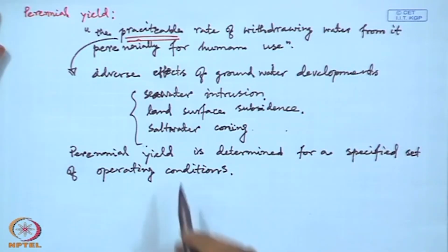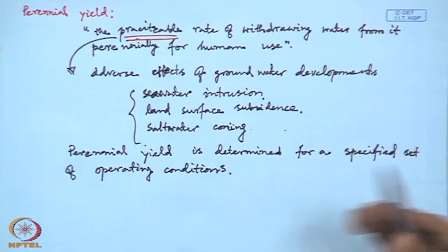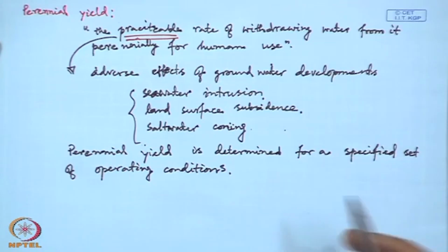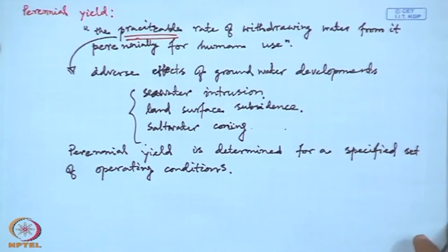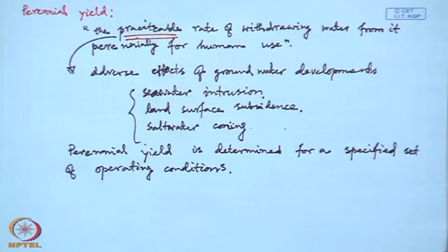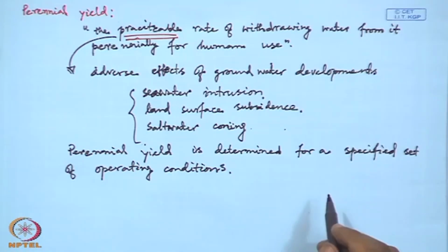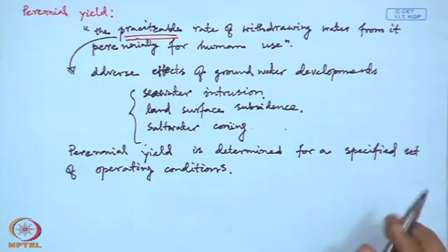So, this perennial yield is similar to the perennial flow in our surface water systems, and the perennial yield from a designated reservoir would be achieved if artificial discharge by the well were pertained so as to reduce the discharge from reservoir and induce recharge in an equal amount, and if storage were utilized only to provide some kind of regulation of the fluctuating inflow and to meet the demand of the well.